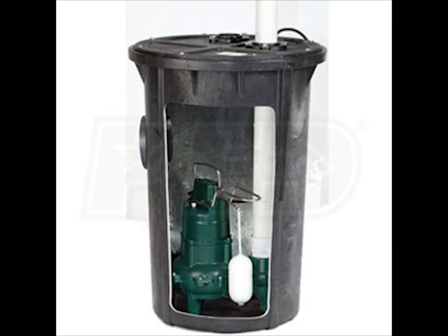The sewage pump discharge requires pressure-rated piping, not DWV piping. The red-lettered 2-inch pipe is dual-use, pressurized and non-pressurized. It also needs a gate valve on and off so as to service the pump if needed. This will stop flow from above. I bought a Zoller 30-0151.